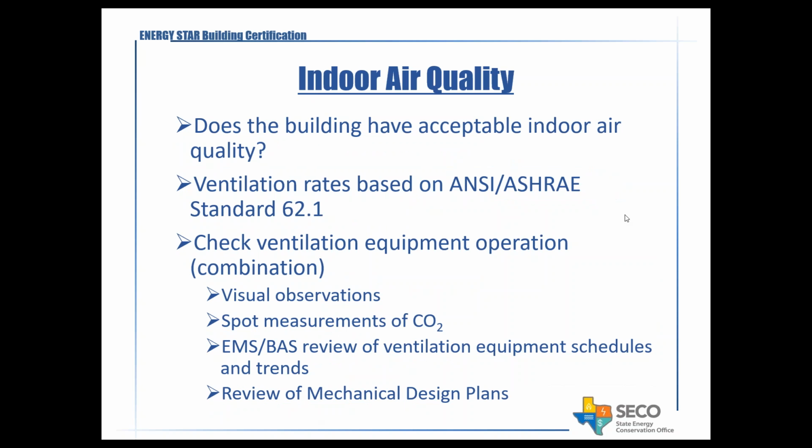The next thing to check would be the indoor air quality. So really they're wondering, does the building have acceptable indoor air quality? This would be based off of the ventilation rates in the ANSI/ASHRAE Standard 62.1. We're not going to go into that. It's a bit too much information, but there are multiple ways that we can check these things, and sometimes we just do a combination of them.